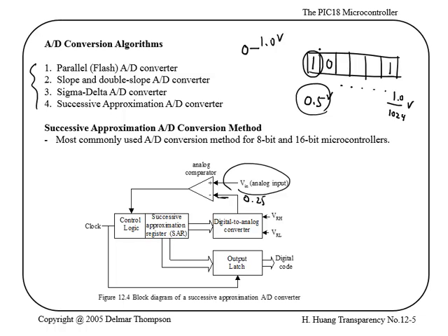Now, every single one of these bits is going to take TAD time, right? So to convert one whole 10-bit value, you need at least 10 times TAD to do the conversion. And this TAD value you have to pick from the specific PIC value that you have. We will deal with this later, how to pick the values. And in fact, PIC is not going to do 10 times TAD. It's going to do 12 times TAD or 13 times TAD, because it does need some time to reset these devices and the internal capacitors and so on.